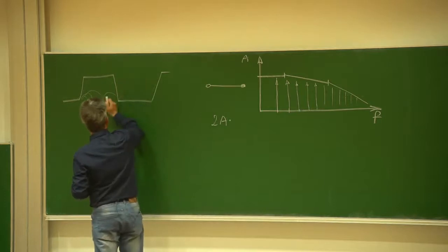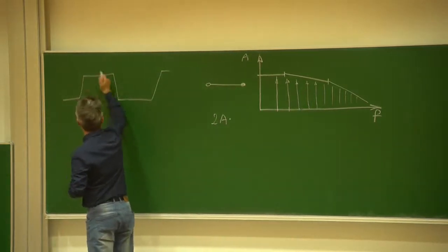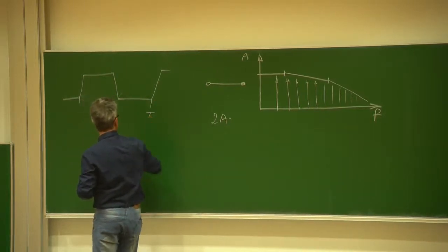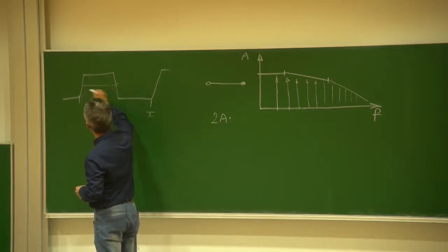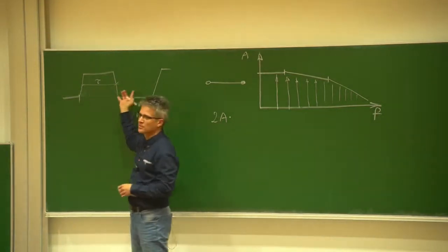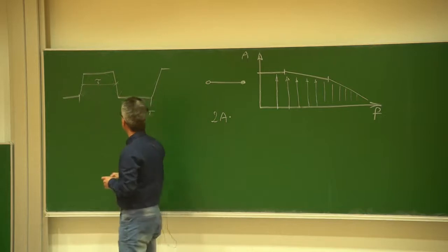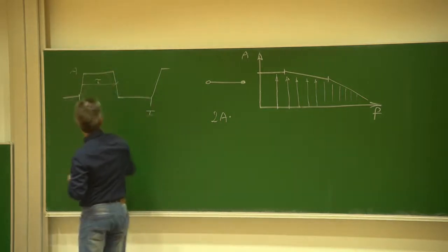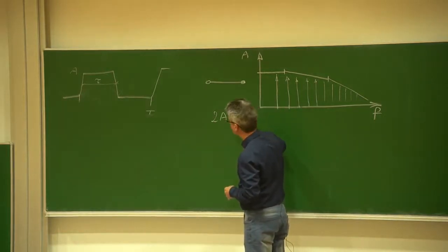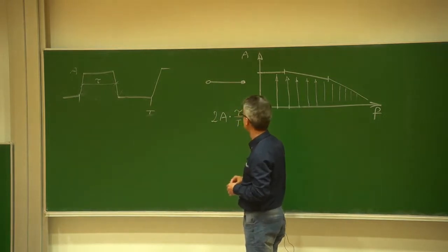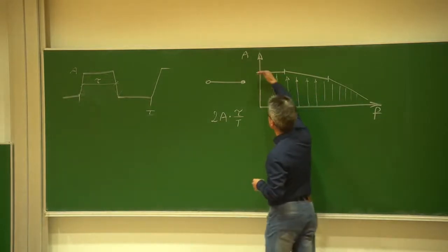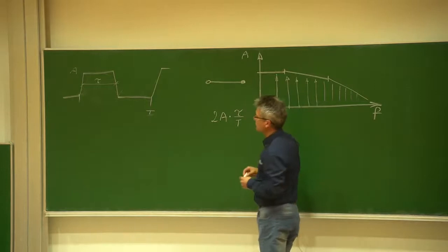no, I have to define some things here. We have, from here to here, the period T, and from here to here we have the high time. In our case, the high time is exactly the same as the low time if you have 50% tau. Okay, this here is then the amplitude. I hope I'm correct. This is then 2 times the amplitude times tau over T. Then 20 times the logarithm. So this is defining the value here of this horizontal line.